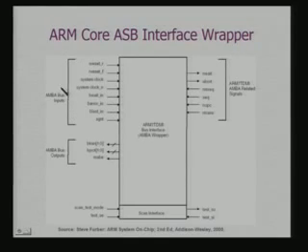this is basically the ARM7TDMI AMBA related signals which are directly available, and these are interfaced onto the AMBA bus. You will find that the HREADY signal that we had discussed in case of the AHB bus is here BWAIT in, because the definition is slightly different in the ASB bus. This is BWAIT in, which is equivalent to nWAIT on the chip itself.